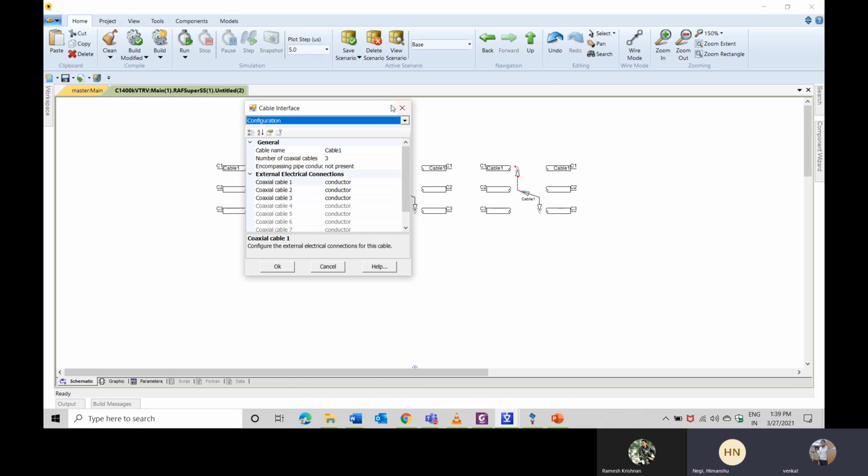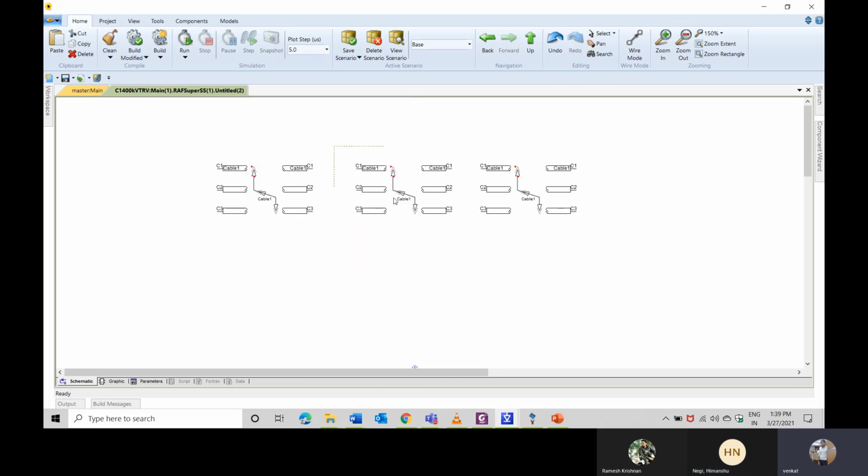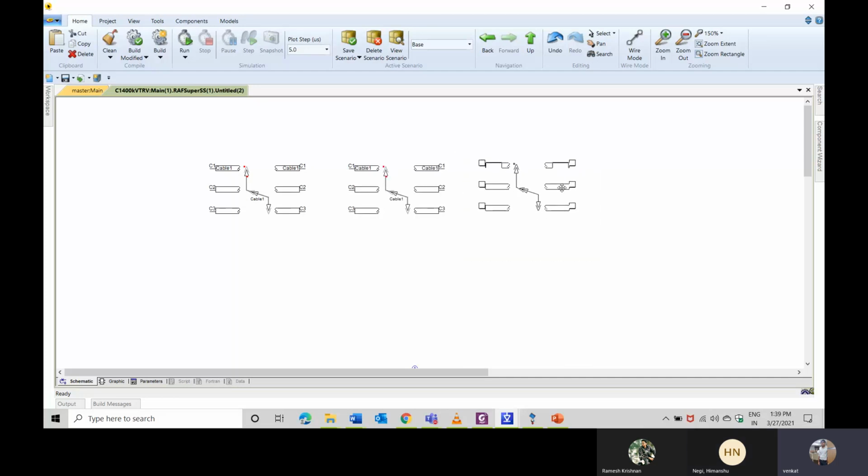Now, if you are going for, like you have asked for, ideal transmission of cables, then what we used to do is take this as a single set, then this as a second set, and this is the third set. And then we have to manually transpose them.